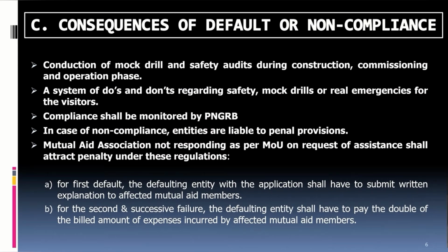Third point is consequences of default or non-compliance. To ensure that all the regulations are being followed and implemented, mock drills and safety audits must be conducted during construction, commissioning, and operation phase. If there is any outsider visiting the plant, he should be made aware of all the do's and don'ts regarding safety and emergencies. PNGRB will monitor the compliance of ERDMP, technical standards and other specifications.